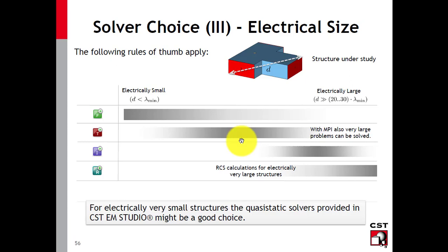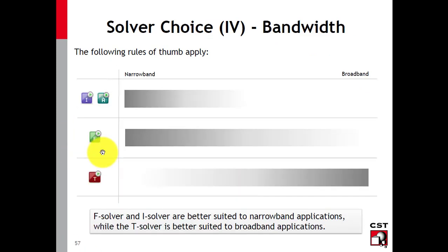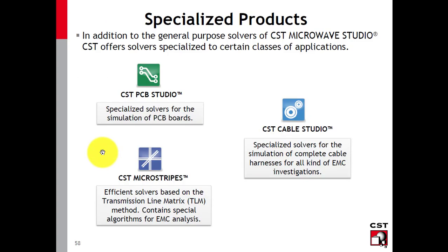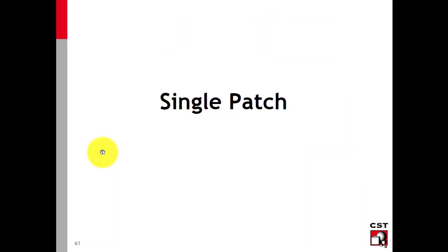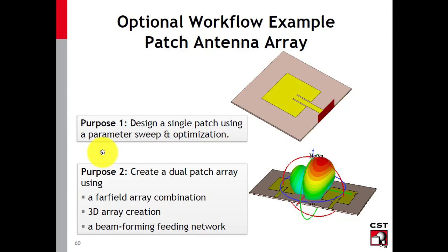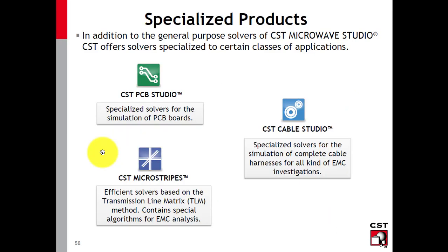Because maybe you have an airplane. An airplane has big, electrically large dimensions. So for it, you can use the integral solver or integrated solver. So we can choose the types depending on the shape we have, the size we have, or the properties of the application we have.